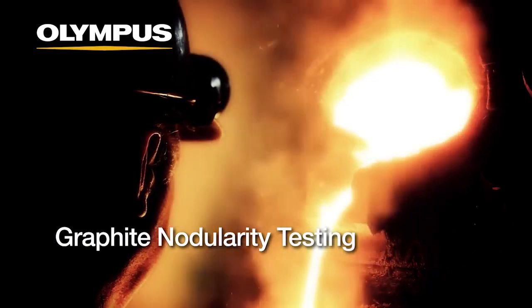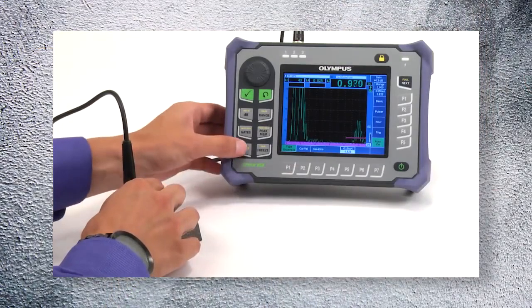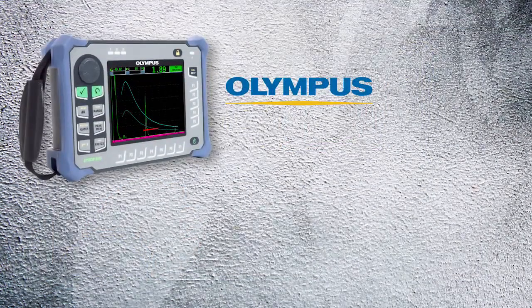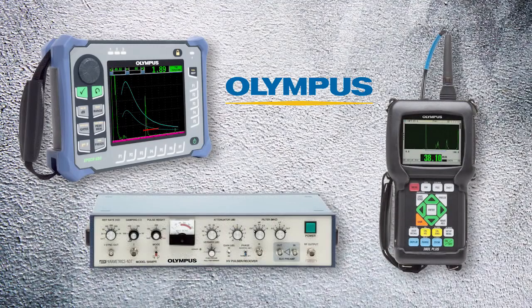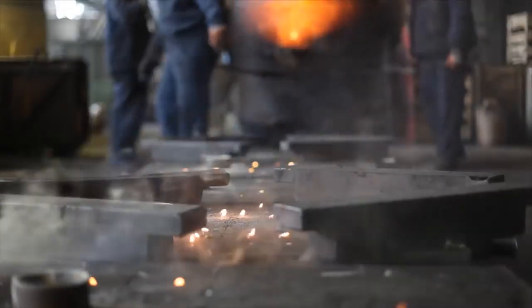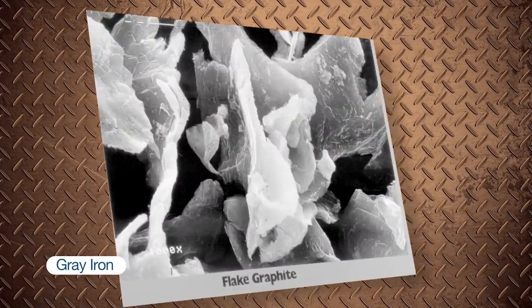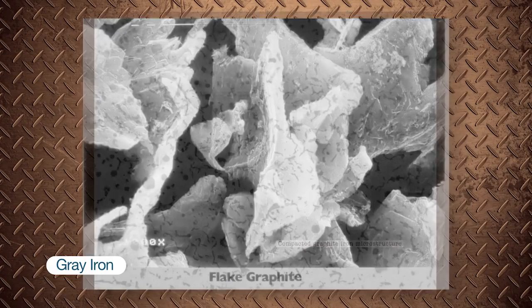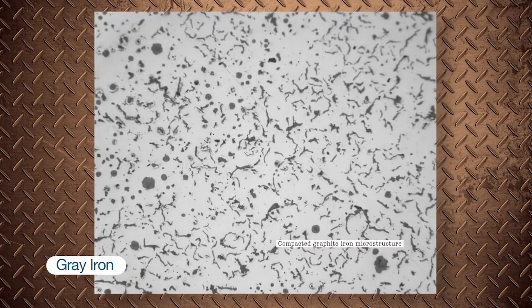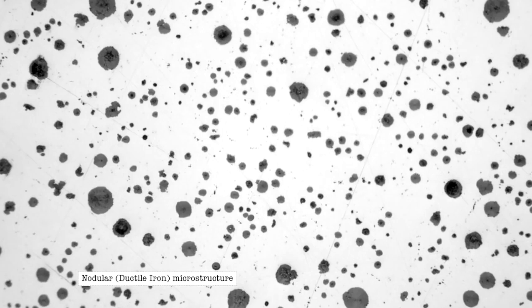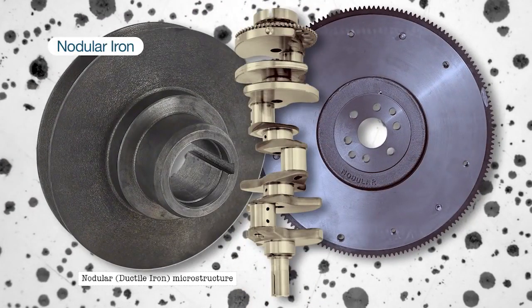Graphite nodularity testing in cast iron can be done with any instrument that is capable of measuring sound velocity. This includes an Olympus ultrasonic flaw detector, ultrasonic thickness gauge, or a pulsar receiver system. The practice of adding graphite to cast iron is commonly used to enhance the material's mechanical properties. Gray iron is formed when added graphite arranges itself in the form of thin flakes. This results in a more hard and brittle iron. The more desired graphite microstructure is in the form of spherical nodules, which produces a more soft and malleable iron. This material is known as nodular iron.